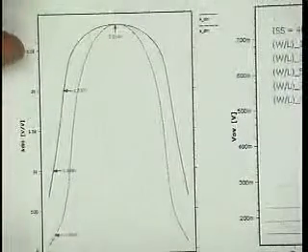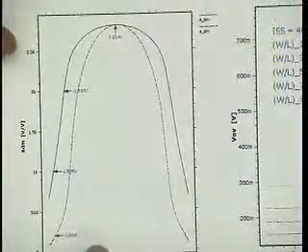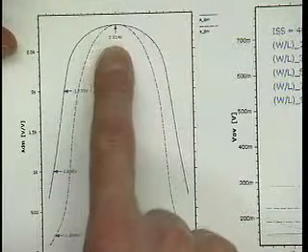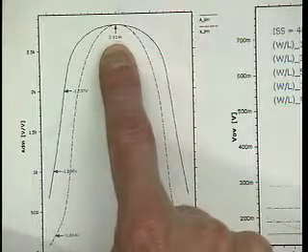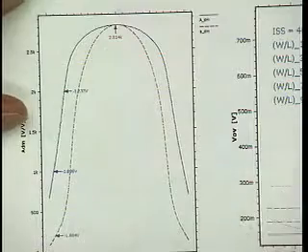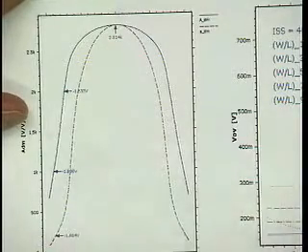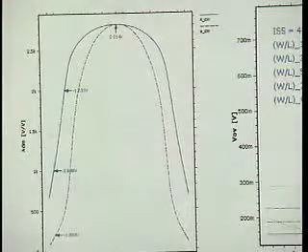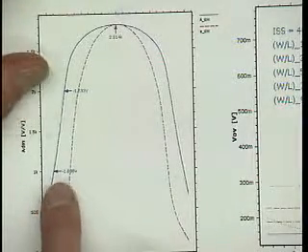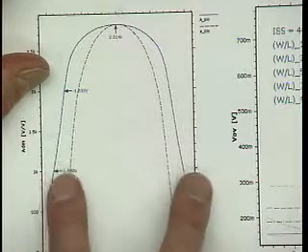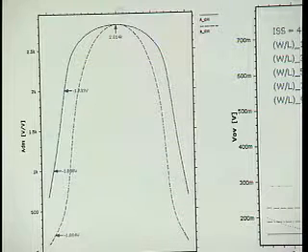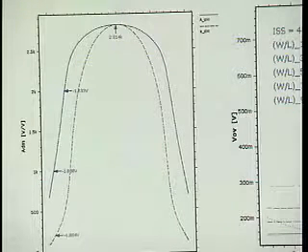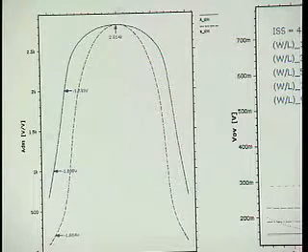So then the gain goes up to 2,800, but that's from 200 some, right? Really more than an order of magnitude. We increased the channel length only by a little bit, less than a factor of 3, and the input diff pair we didn't change at all. So now for plus minus 2 volts, I get almost a gain of 1,000 instead of 120 before. So if we can afford using devices that are just a little bit longer than minimal channel lengths in most processes, that will do a lot for the gain.